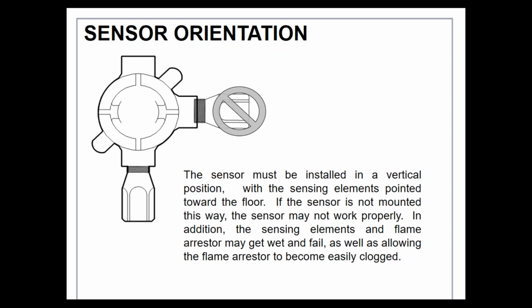There was absolutely no physical way for that sensor to be pointed down in that application. So we came up with a method to show the customer, Atlantis Sub, how to orient the sensor internally so that the active and the reference bead are in symmetry. They're left and right rather than top and bottom. Now when they install it, they mark the sensor, turn it to the right orientation, and it's been working for them for about 15 years now. So we can do things to get around certain problems, but the rule of thumb is that it should be facing down most of the time.